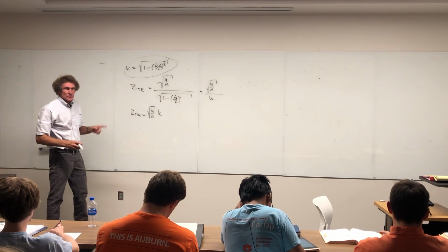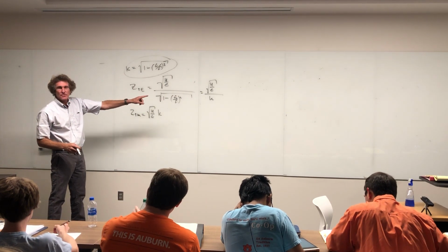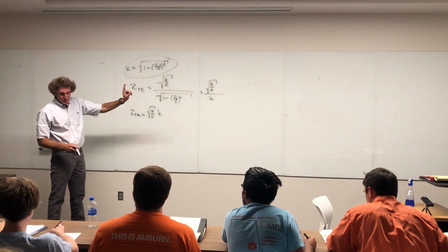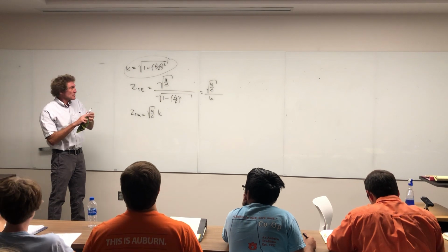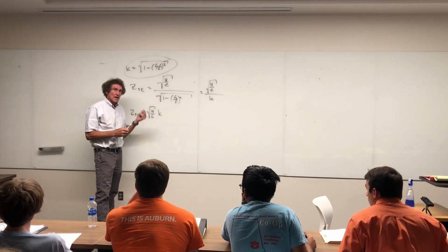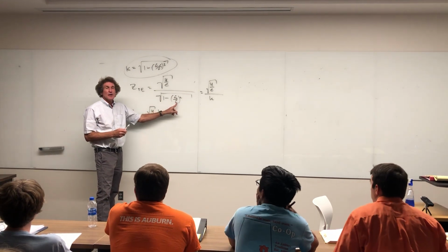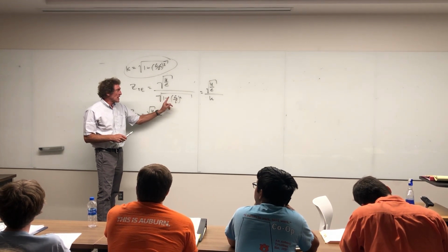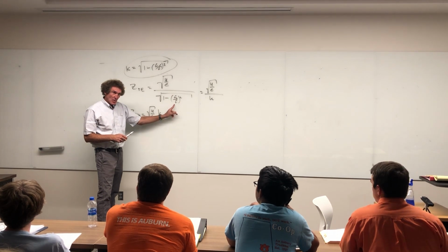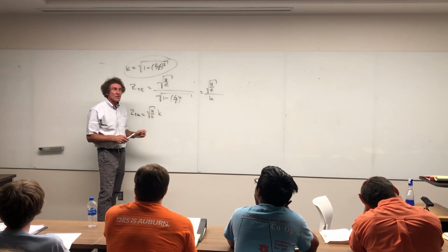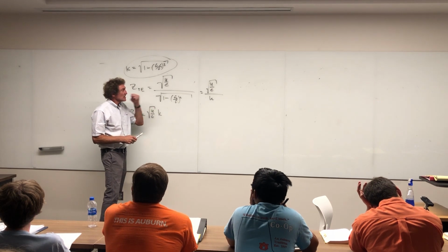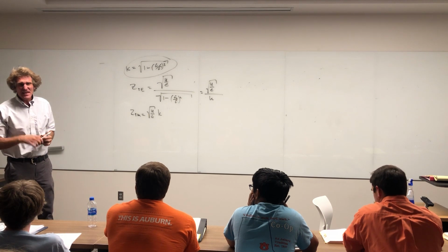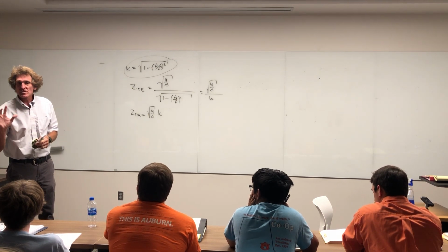Now, TE modes, as you get close to cutoff, that impedance goes to infinity. Do you see that? So this is important. When you've got a TE mode, which most of these are, the 1,0 mode, just think about this: what happens if you're at, say, twice cutoff? Well, then you would have 1 minus 1/4, or 3/4, so you would have the square root of 3/4, wouldn't you? So it would be really the characteristic impedance of the media divided by the square root of 3/4. That's about the characteristic impedance of the media, so it's not a big problem.